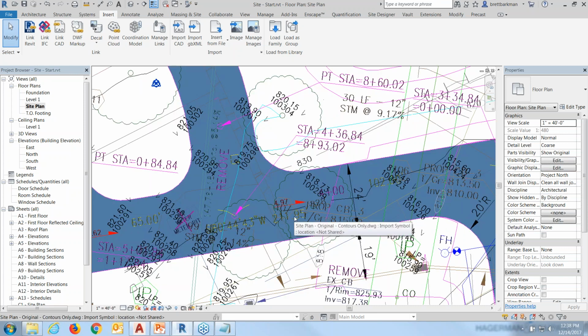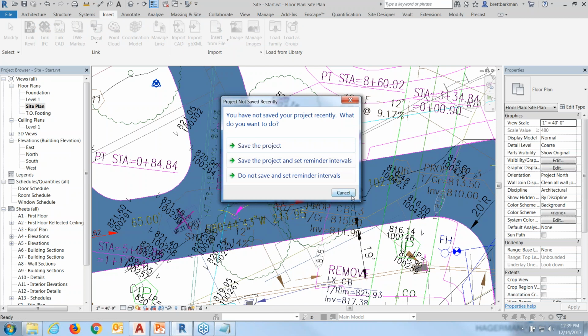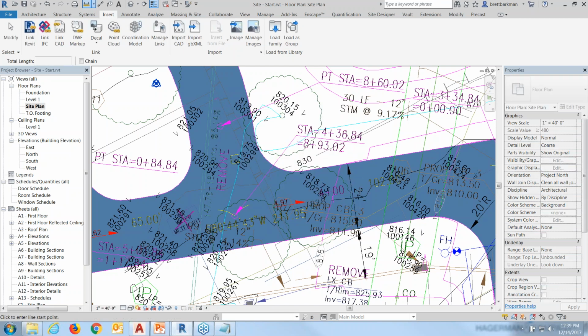this drawing is. Even though everything looked good on the CAD side, it's a civil drawing, and there's a very good chance that we have a feet versus inches or a scaling issue. So we want to verify that first thing. So I'm just going to go to the measure tool. And let's see, this says it's supposed to be 24 feet. So we'll take a measurement from here and we'll just get close.